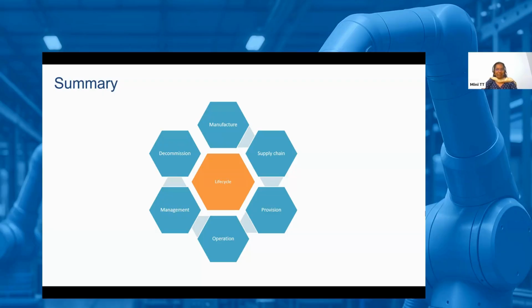So online direct update for critical infrastructure is not the recommended way, because it's not safe to do, because all these systems which we are talking about are also safety critical systems. It's not just reduced functionality once it goes down, it can also affect the safety of your network. They are critical, that's what we are talking about. So online direct update, you can still call it online, but it may be locally hosted, verified and qualified patches. Right, and it's assuming you get the patch from the actual vendor as opposed to from the operating system.